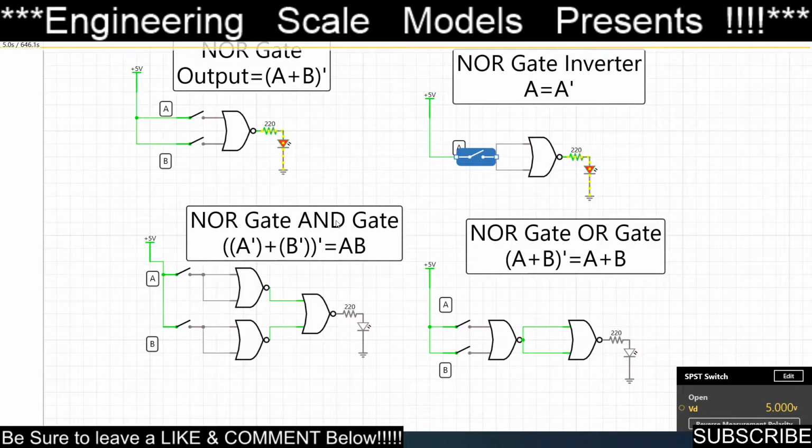Now for an AND gate, you connect one NOR gate, you take both inputs to an A input, and on the second NOR gate you take both inputs to a B input, and then both those outputs feed into the inputs of another NOR gate.